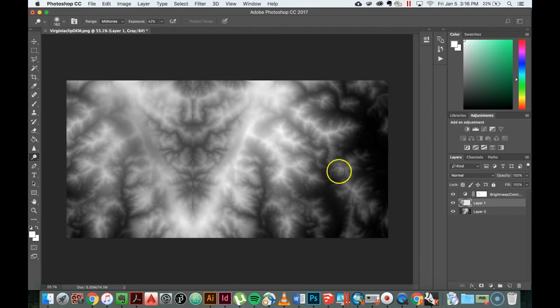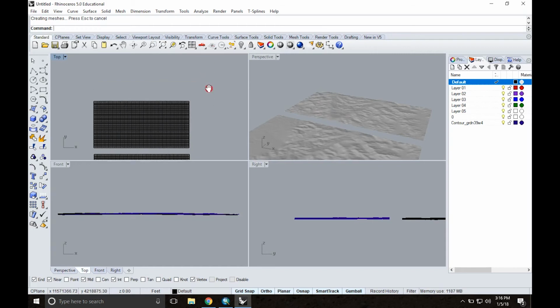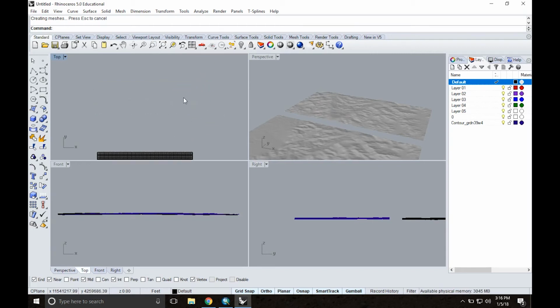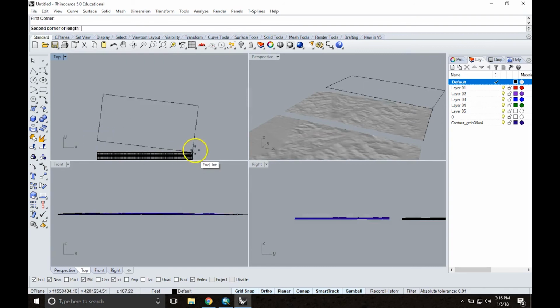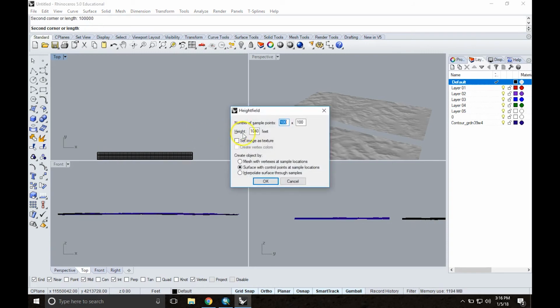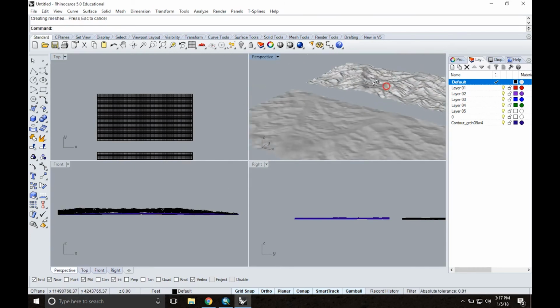So then you can just start playing with the grayscale values, and that will help you generate something like this. And then remember that you can also change the height, so if we wanted to exaggerate this topography for some reason, we could also do that. So instead of doing the appropriate amount, if we wanted to play with this, we could exaggerate and make this like 4,000 feet. And then you see that we get some really exaggerated topography over here.